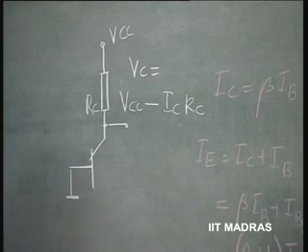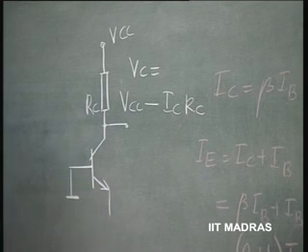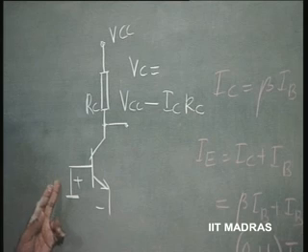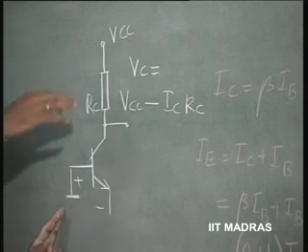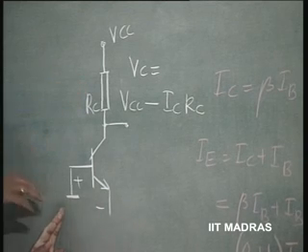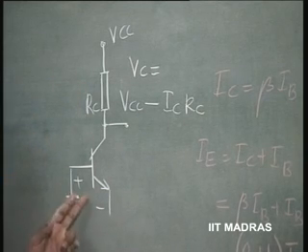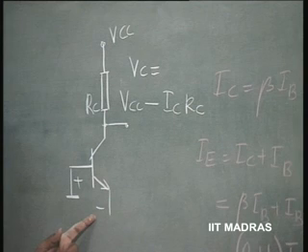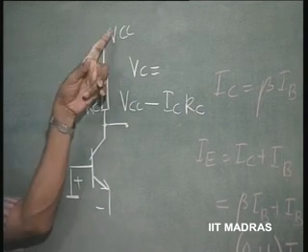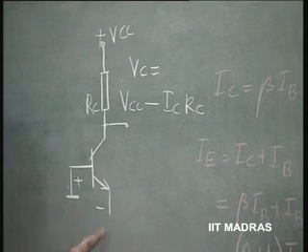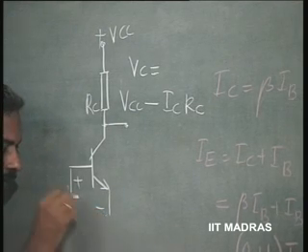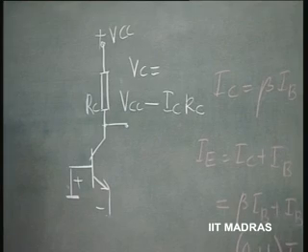The collector voltage with respect to the common point, whatever it may be. And the emitter voltage now has to be negative, because it is VBEQ; base is made common. With respect to base, all the DC voltages and AC voltages are measured. So, base is common. Now I have to necessarily use a negative voltage, because the emitter is at a positive voltage with respect to base. That means I could use VBEQ, which is negative, appropriately chosen, so that this current is there.